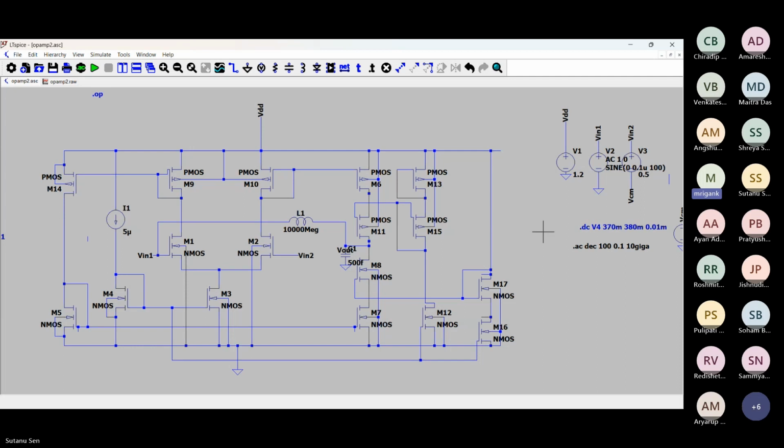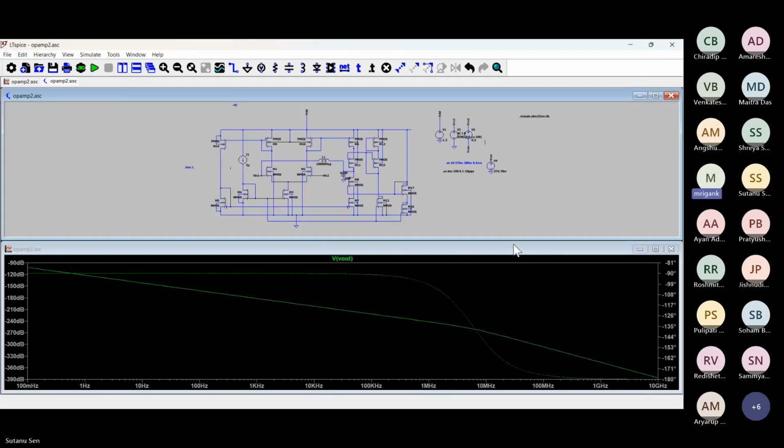There is the open loop analysis setup where you don't have to necessarily open the loop and fix the DC point, just like what we are doing here. But here this feature is not available. So this is an alternate trick just to avoid that DC sweep.